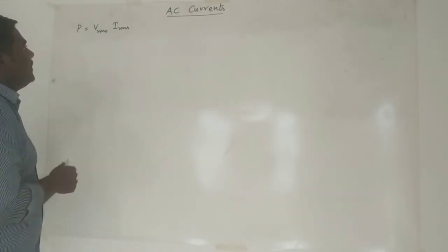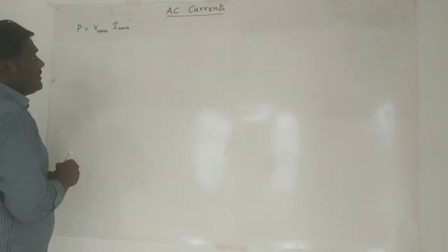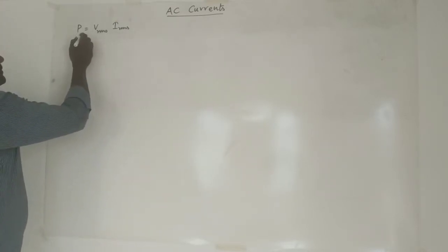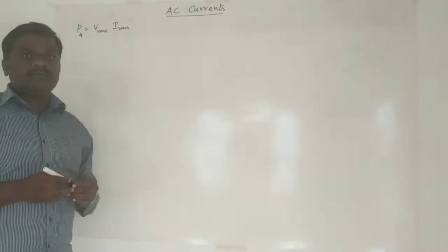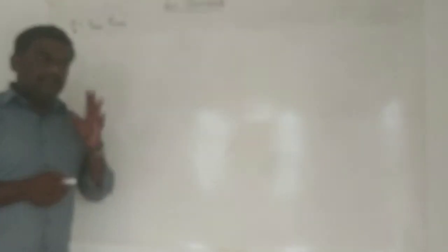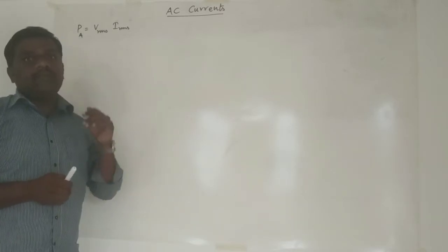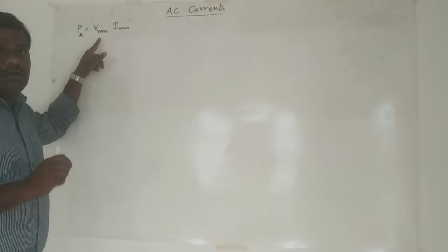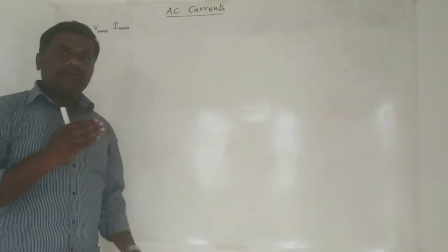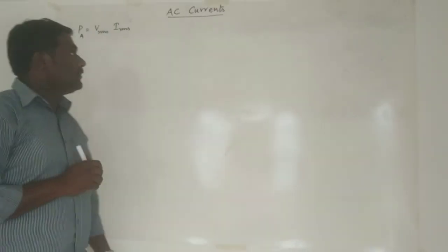So here, for calculating power also, I took power as the product of VRMS and IRMS. This product of VRMS and IRMS gives a power known as apparent power. What does it mean? This is the power actually supplied through the circuits. For example, our household takes a voltage close to 220 volts, somewhere in the range of 220 to 240, though usually 220 is the actual voltage required.